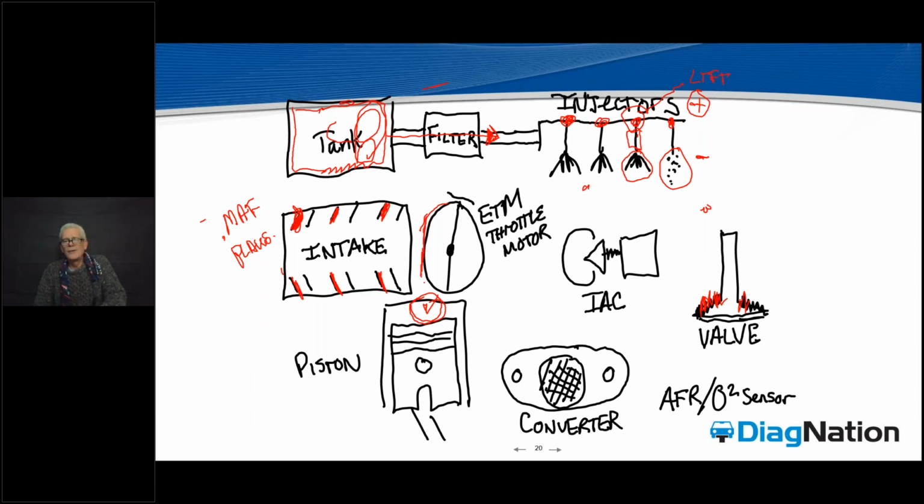But I want you guys to consider that beautiful, hard, carbonaceous ring that we've been cleaning off the backs of throttle plates for 35 years now. Now, that throttle motor doesn't have an IAC bypass, so as that ring of carbon builds up on the back of the throttle, what's its only course of action to fix that? It has to crack open a degree or two.